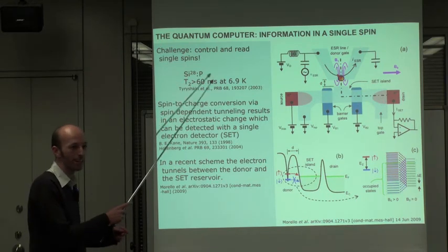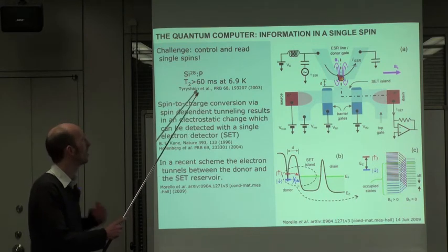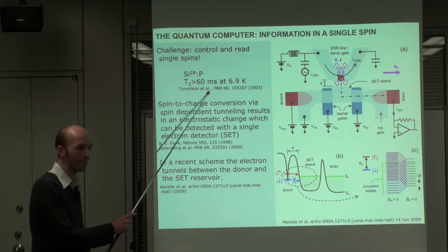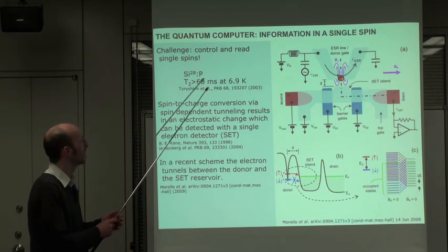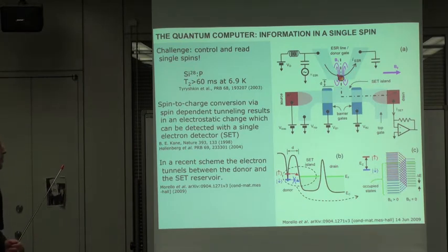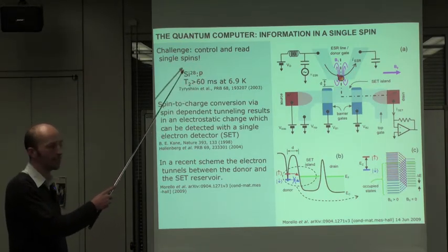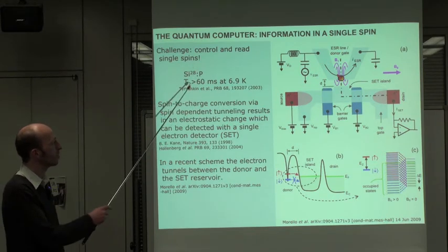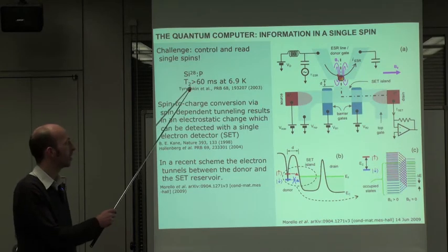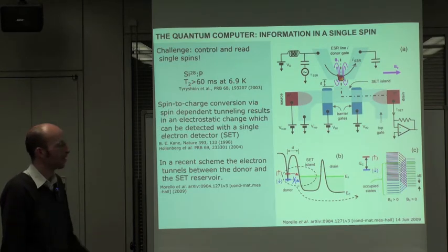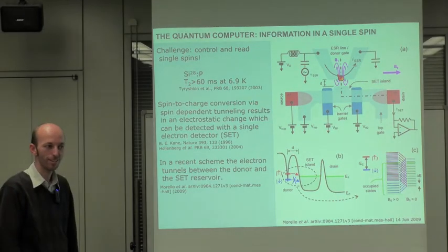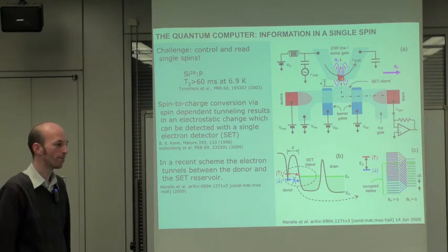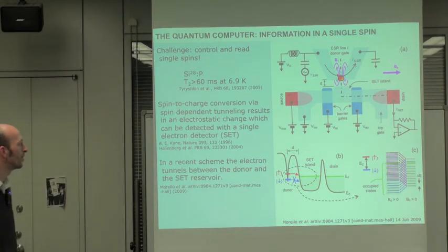I should change this now because I saw some new measurements which I think increased this number by Professor Ito. Anyway, this is an attractive system because of the long coherence time, which is limited by the silicon-29 concentration, and this can be decreased by processing, as you well know.